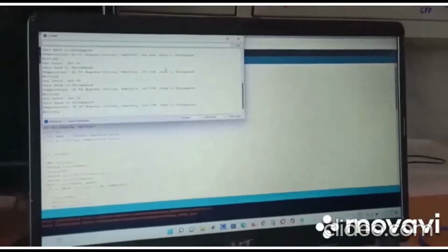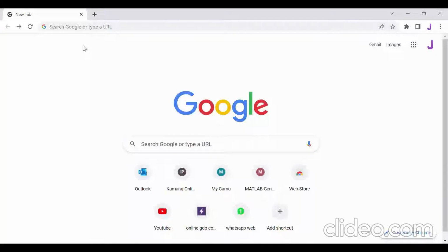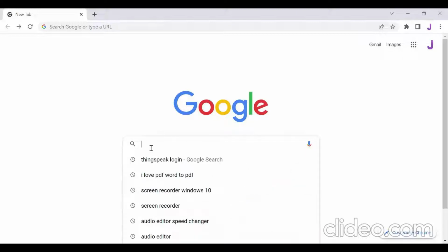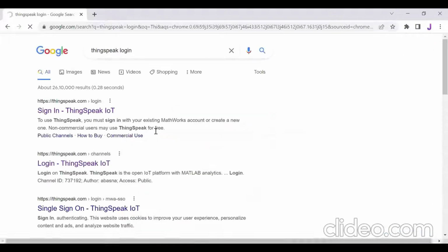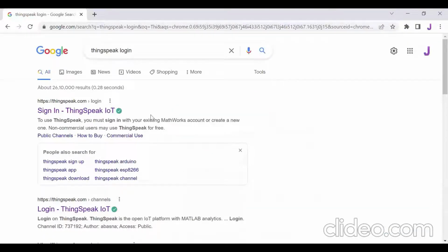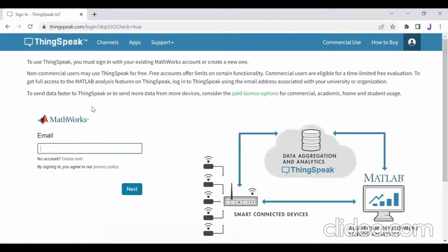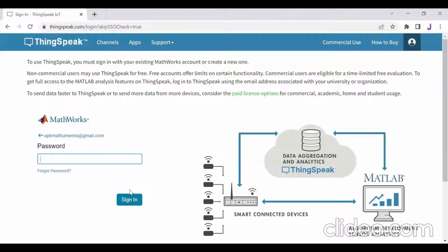Its detection intensity is about 300 to 10,000 ppm. DHT22 is used for detecting ambient temperature and humidity. Measuring range of temperature is about minus 40 degrees Celsius to 80 degrees Celsius, and humidity is about 0% RH to 99.9% RH. These two sensors send the data through the microcontroller of ESP8266 Node MCU, which has a built-in Wi-Fi module in it. Node MCU is programmed using Arduino IDE.